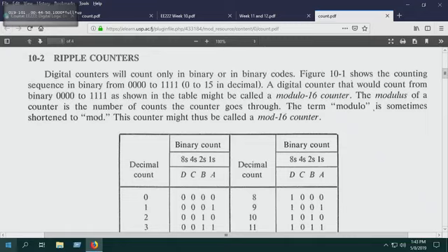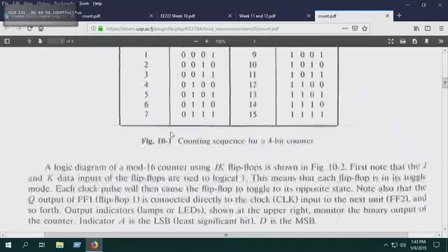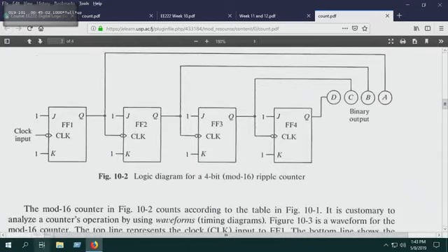They start to fall in a line, right? That's called a ripple. So what's happening here is the way this thing is structured. It is working in the form of a ripple counter, which means in order for the second flip-flop to get triggered, the first has to trigger. For the third one, the second has to trigger. For the fourth one, the third has to trigger. So it's a rippling system. Another word is ripple counter, another word is asynchronous counter.